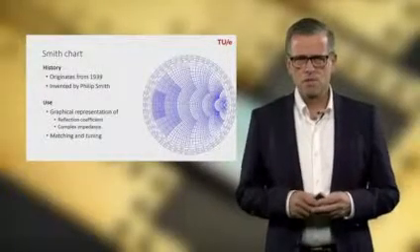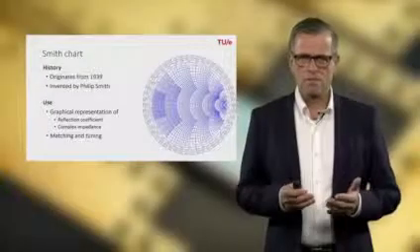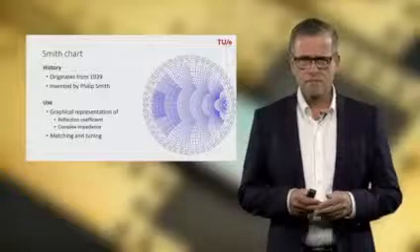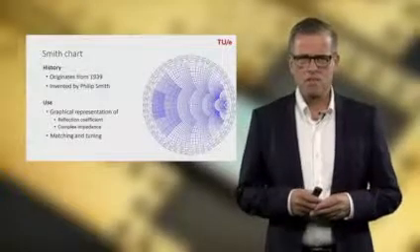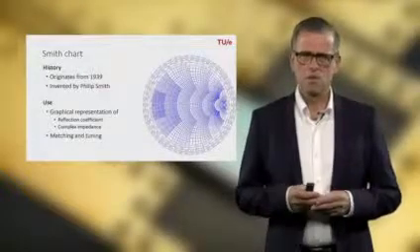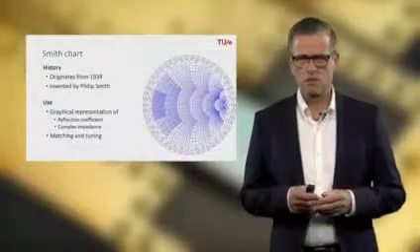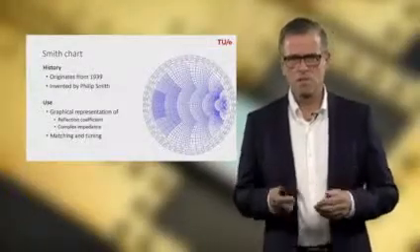Now, the use of the Smith chart is to make a graphical representation of the complex reflection coefficient and the complex impedance, and it's very useful when you are designing a matching or tuning circuit, as we will see in one of the follow-up web lectures. The Smith chart might look rather complicated at first sight, but in fact it's not, because we're only plotting the complex reflection coefficient in the complex domain.